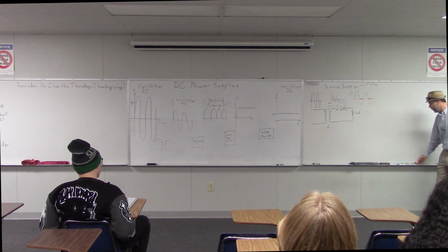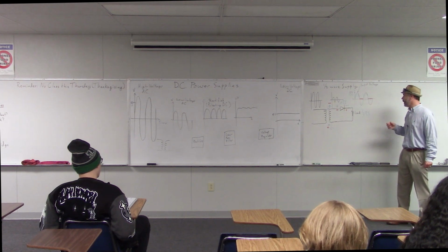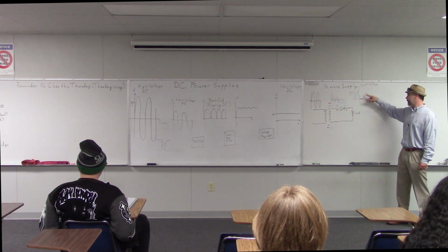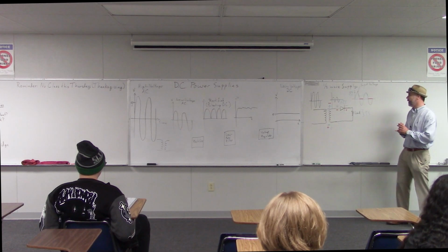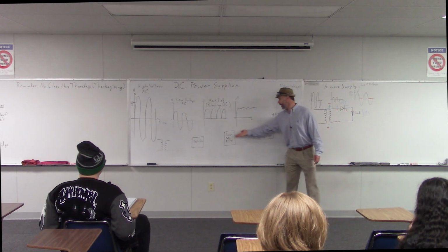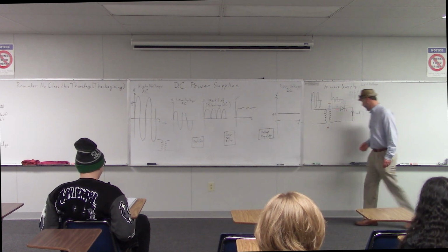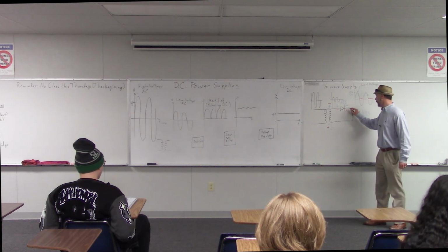Okay. So that would be the voltage across our load. Now again, this output signal has these big dips in it and big changes, and that's not great. We're trying to get to a nice flat signal. So what we need is to do some filtering. We want to smooth that out. So again, the easiest way to do that, the simplest form, is with a capacitor.